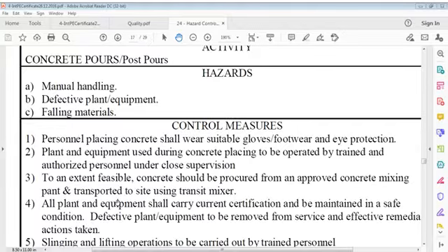But it's strong enough to take the load, and then you have to put girders on that, or some horizontal members so that you can fix in that. It should be strong enough. Your access to that level should be strong enough. If you provide temporary stairs, they should be strong enough. We have to see every point. All side supports of the beam should be strong enough.